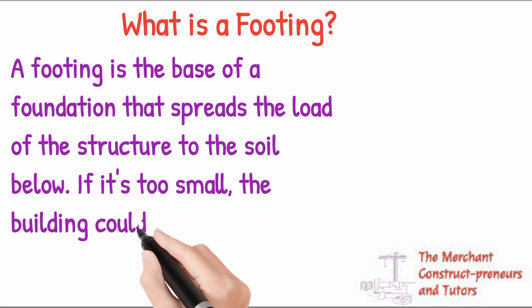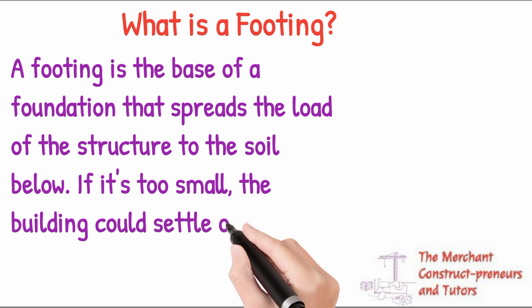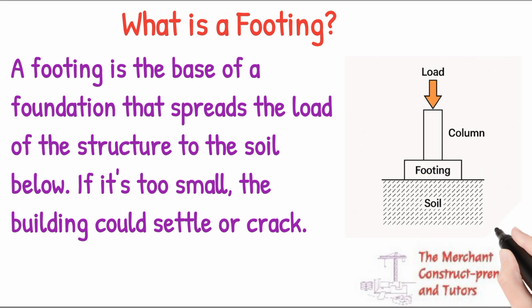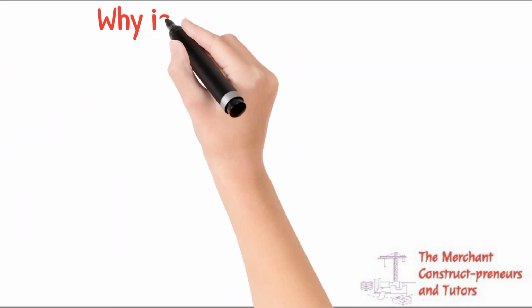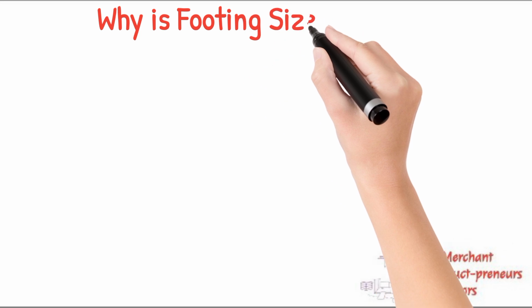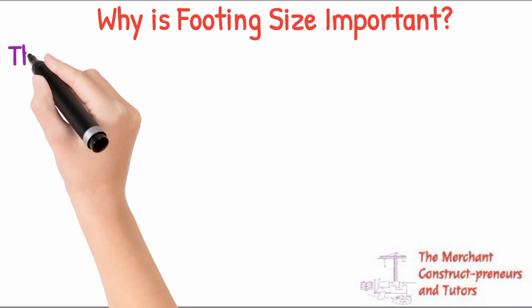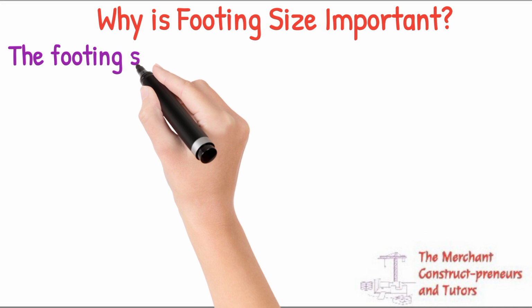If it is too small, you might not be able to carry the building, then the building will settle or crack. Look at the image, you can see the load transfer: load to the columns, to the footing, then to the soil. That is what the footing does. It collects the load and then spreads it to the soil.